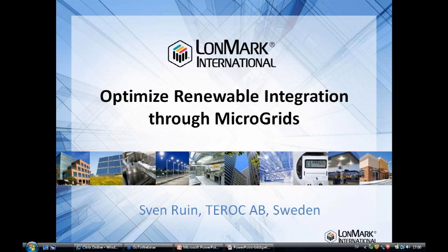So in this webinar, I will be talking about small-scale renewable energy, such as solar or wind power, and how to integrate them in microgrids. A microgrid is a localized grouping of electricity generation, energy storage, and electric loads connected by a small electric network, usually using low voltage AC. Such a microgrid could operate either connected to a central/national grid or could be completely separate. In any case, the microgrid can function autonomously.